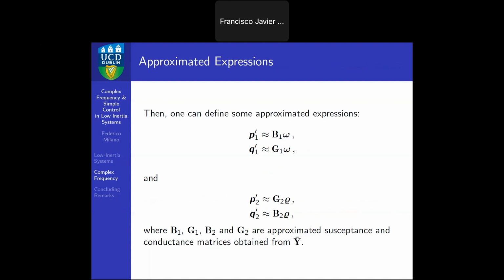And in fact, if you do some approximations, you see that there are these links, okay? This is the classical DC power flow, the derivative of the classical DC power flow. And it's okay for a DC network. Now, if your network has very low losses, then this link is super marginal, and you have maybe a strong link between voltages and Q, which is the typical thing that we say, right?